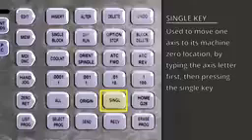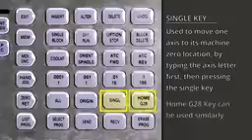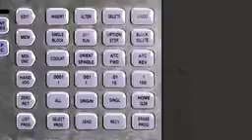This function is often useful with the Z axis to easily raise the spindle, or with the Y-axis to bring the table close to the machine's doors within reach of the operator. The Home G28 key can also be used to home a single axis, again by simply entering the axis letter before pressing the key. The final remaining key in this row is the origin key.